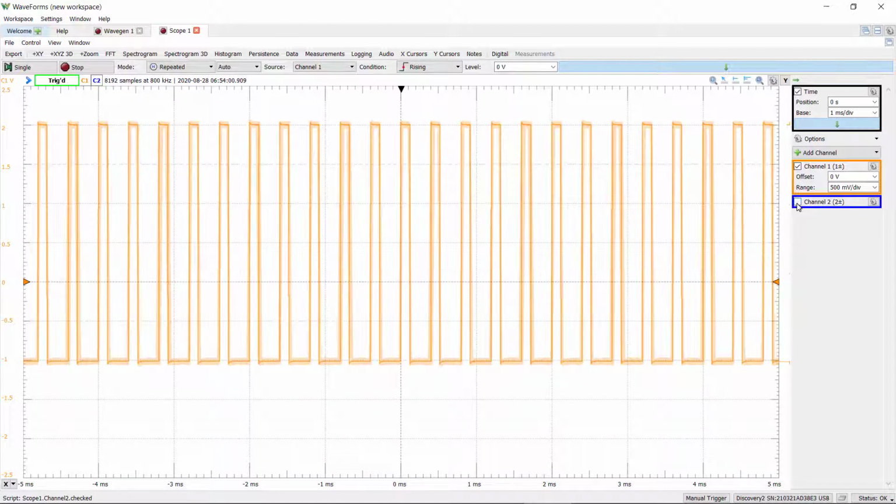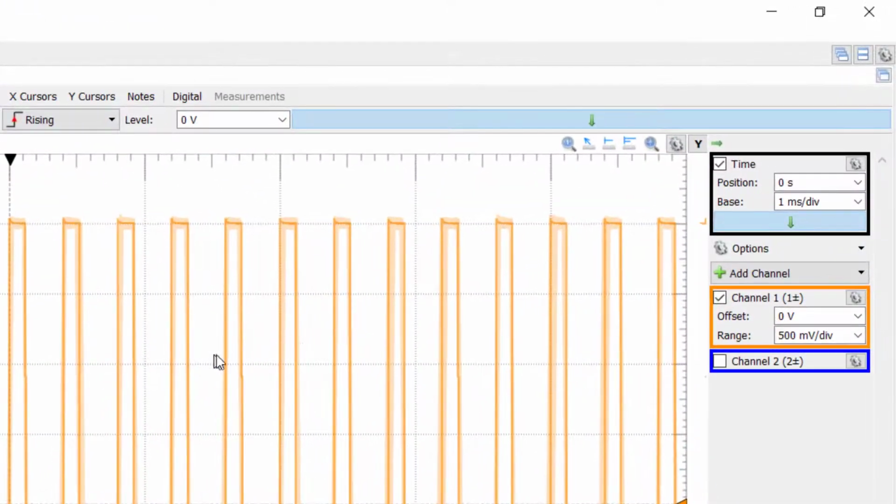But for now, I'm going to turn channel 2 off. So here is our waveform. It's offset a little bit. It's distorted. Now you can see there's noise on top of this because we have RF pickup. We're going to look at that in a later video as well. I recognize there's RF pickup because I have jumper wires. There's very little I can do about that, and we'll see what we can do and how using a 10x probe will dramatically improve that.